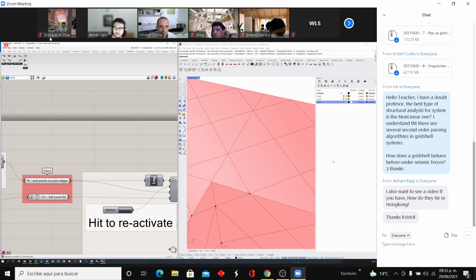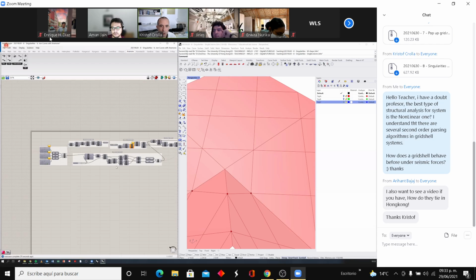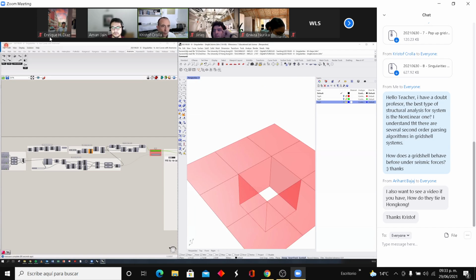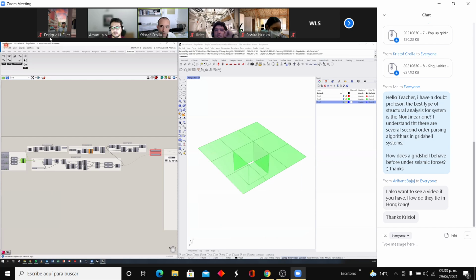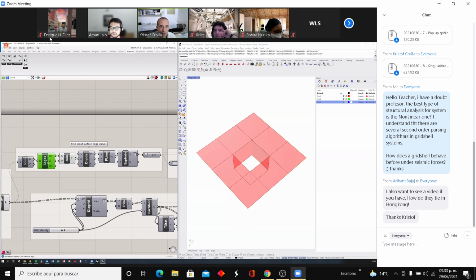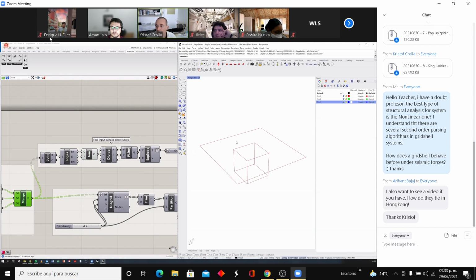Oh yeah, so first I need to identify my points on the edge. So let's see how I did that. So hold on, let me switch this off. So I have my surfaces here. First thing I'm doing is I'm joining all of them and I'm finding the naked edge curves, which are all of these. So by joining the planes without flattening it, I'm joining all the topology A planes, topology B planes, and topology C planes, and I'm automatically getting all the edge curves that are relevant.